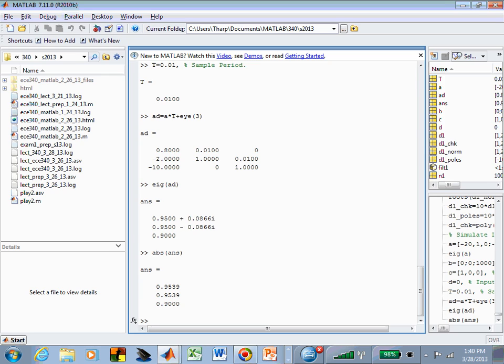If you get into discrete time processing, the stability region now is this finite region in the z-plane, just the unit circle. We've gone from the entire complex S-plane, left half being stable, we've now collapsed that down to just the unit disk in the z-plane. But these all have magnitude less than 1, so our system is stable. That's good. We didn't create an unstable discrete time system by sampling a continuous time stable system.